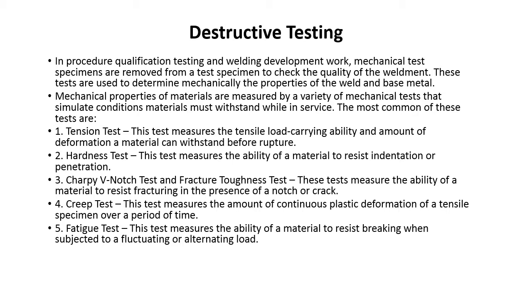The creep test. This test measures the amount of continuous plastic deformation of a tensile specimen over a period of time. The fatigue test. This measures the ability of a material to resist breaking when subjected to a fluctuating or alternating load.